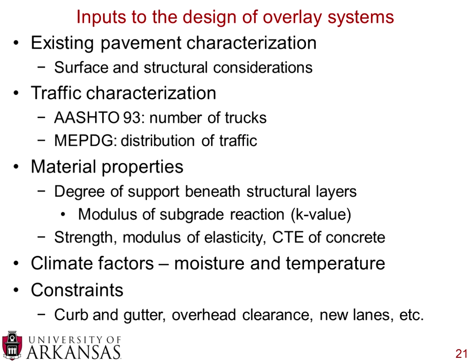Some other material properties of the overlay itself that are important are the strength, the modulus of elasticity, and the CTE of the concrete. And CTE stands for coefficient of thermal expansion. And this is very important because concrete is a mixture of aggregates and cement.